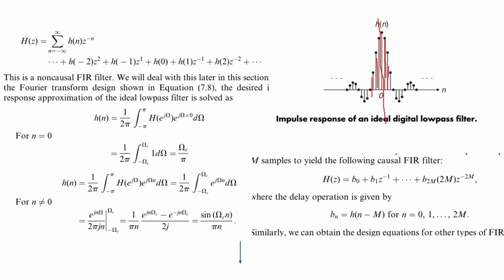So it is very clearly showing, because low frequency is passing now, so it belongs to the low pass filter only. So how will we characterize this? Here H(z) is nothing but the sum of h(n) z to the power minus n, and here the total number of impulses you can write like this. Okay, and h(n) you just take the inverse function of your H(z).